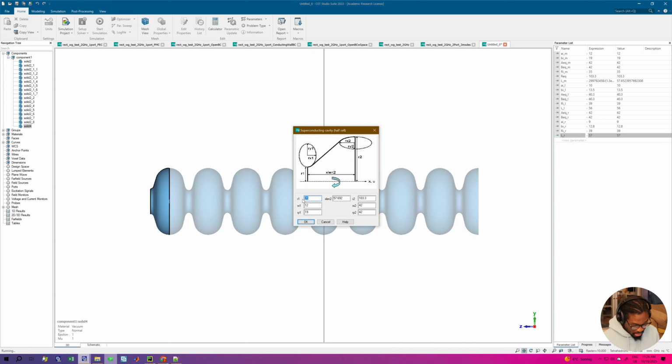Yes, I didn't get any problem. So that's solid 6, and now I rotate it and move it. So transform, rotate. Now I'm going to rotate it minus 90 degrees because I want it to face the other side, to point in the other direction. So minus 90, preview. I hope I'm correct. Yes, it's pointing in the correct direction, so I apply.